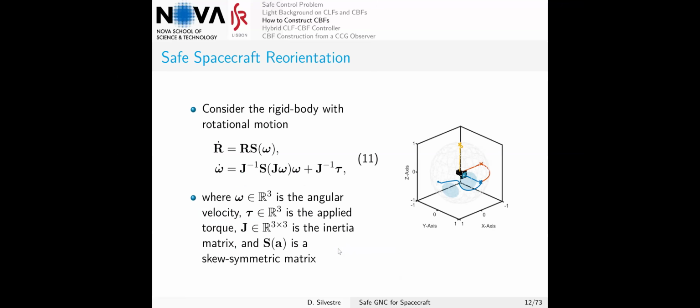So if we are doing this, you could now view these dynamics as being in strict feedback form, because the torques are going to be applied to the angular velocity, but not to the attitude. And of course, we can always do backstepping, which is the same as high order. I've seen in one of the presentations someone say, well, we need backstepping, but there's a paper, I think CDC 24, that shows the equivalence between the two procedures. So you can pretty much pick whichever you prefer.